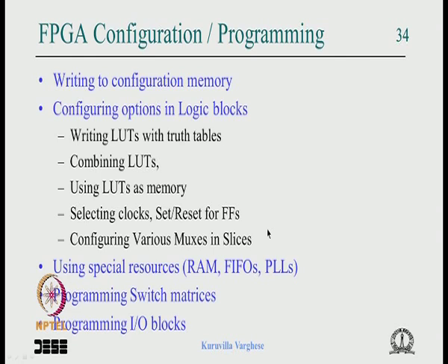Before going further, I want to tell you that when we say we are programming or configuring an FPGA, it essentially means writing to configuration memory. All the interconnection patterns are configured here, all the logic, all the special resources, everything. Within a logic block there are a lot of things to configure.